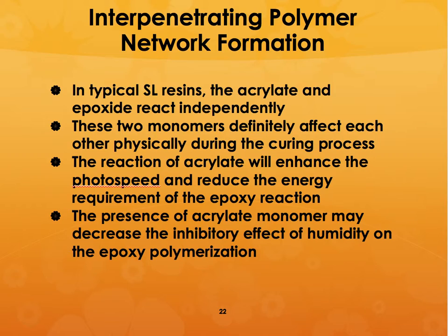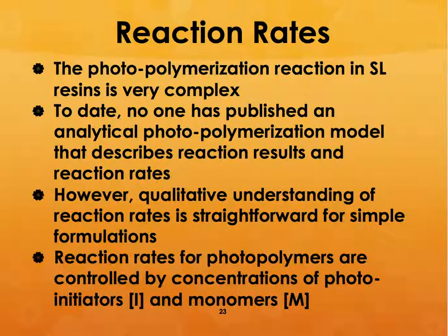The presence of the acrylate monomer may reduce the inhibitory effect of humidity on the epoxy polymerization, because epoxy polymerization can be affected by humidity, but the presence of the acrylate will counter that and prevent it from affecting the curing of the epoxy.